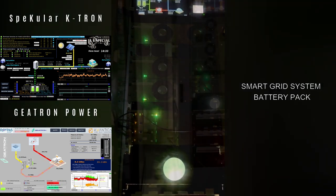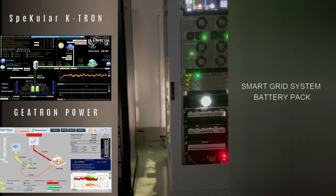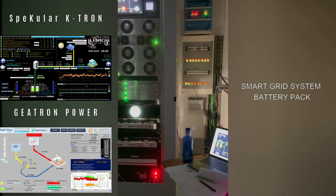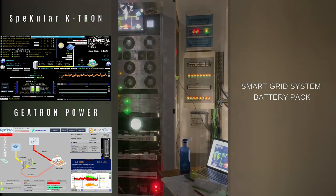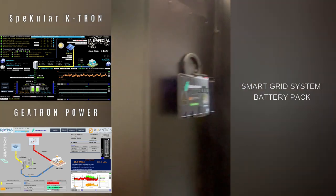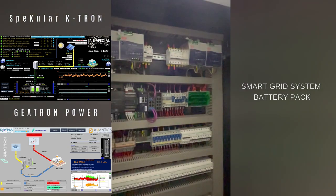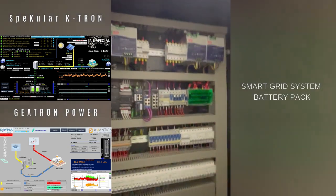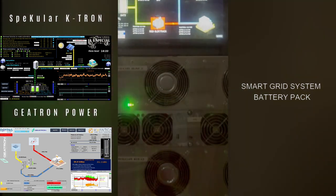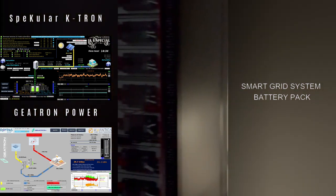The deviation for open circuit voltage is 5% for charge states above 10% and 2% for charge states below 10%. For continuous charge and discharge cycles, the charge rate is 1C for states of charge below 60%, and the discharge rate is 1C for states of charge above 30%. For 30-second pulse charging and discharging, it reaches a charging rate of 2C for charge states below 60% and a discharging rate of 2C for charge states above 30%.